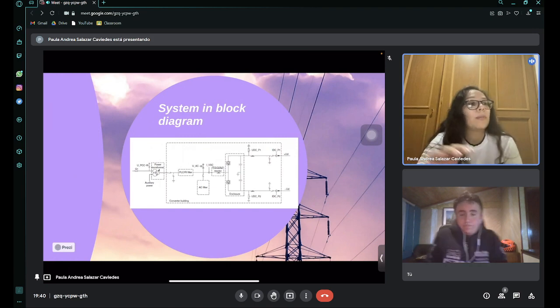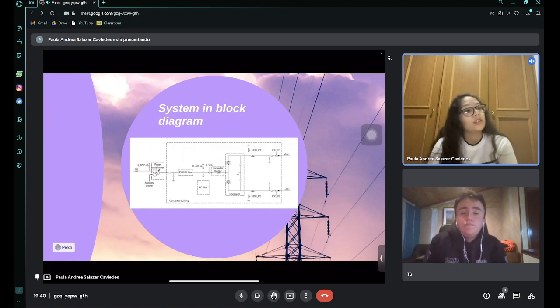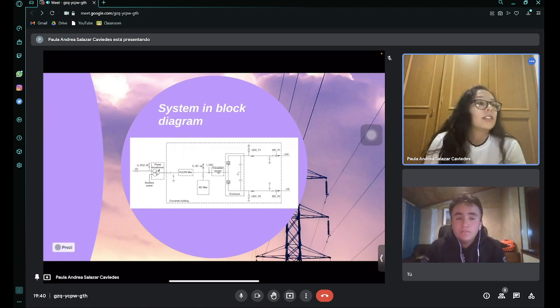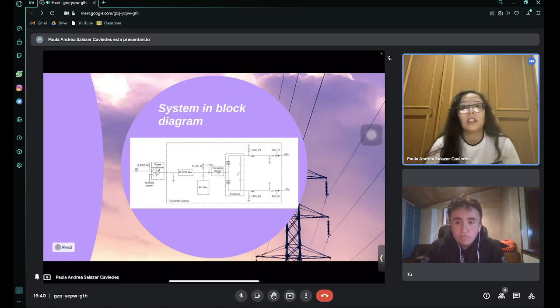Also, we have an important part, which is all the DC capacitors that we have around the system and the circuit. The primary objective of the valve DC side capacitors is to provide low inductance. Also, they help to reduce the harmonic ripple in the DC voltage.